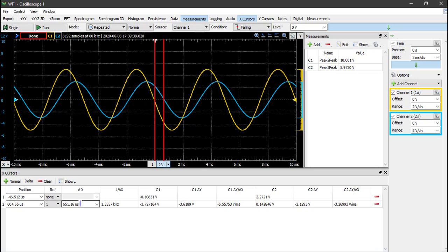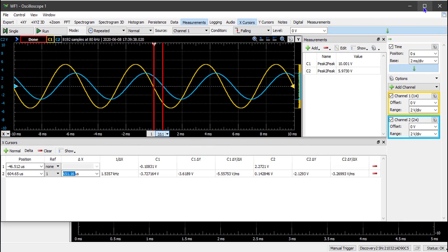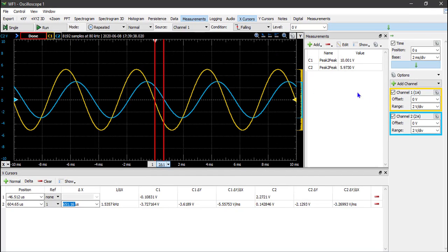Now, the reason why the phase shift increases even though the time delay is decreasing is that you have to look at this time delay over the actual period, because you have to keep in mind the period also decreases. So if you look at the ratio of the time delay over the period, that continuously increases, which is why the phase shift increases. So this looks good. I'm happy with the output.